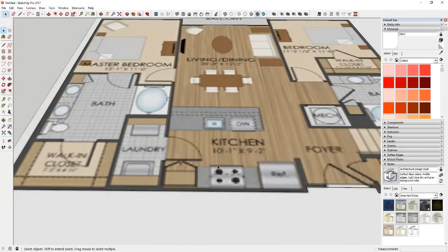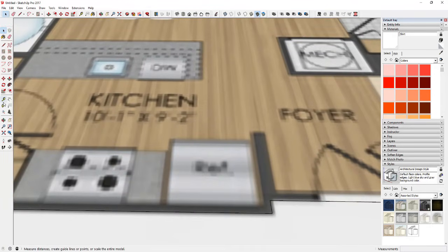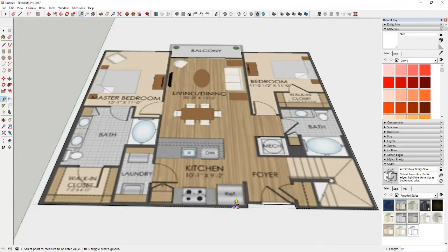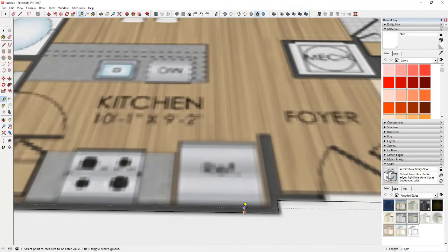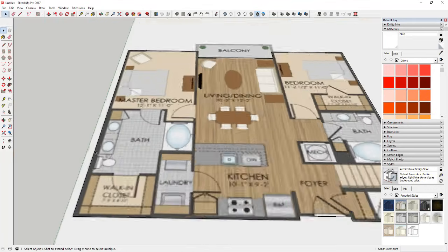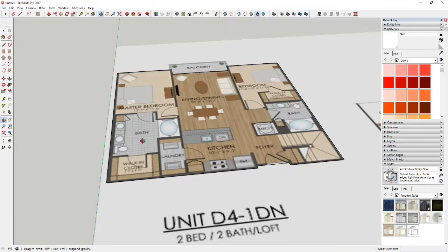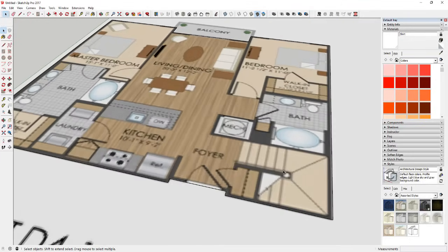And so what I'm going to do real quick is I'm going to delete that face out, and I'm just going to come in here and check the thickness of my wall. Usually, see, that's interesting. You know what this might be is, since this would be an apartment, it may be assuming that these exterior walls over here probably have a thickness of about 3 5/8, or kind of a standard wall thickness, while these are probably thicker because they're probably exterior walls. Yeah, you see how this is about a 6-inch wall? And so that is interesting to me.